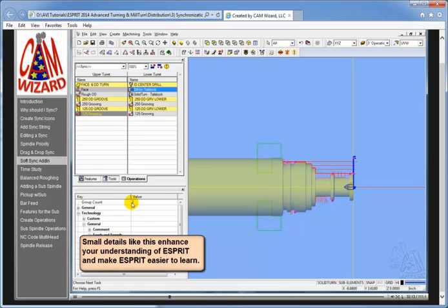You'll see that the group count changed to 2. That's because I didn't have to use a control key. It looks at each column as independent. I would only use my control key if I was picking multiples within each of those columns. So in this case, I have both of these operations grouped. Now, when I go up to pick on this add sync code, you'll get a dialog box that pops up.